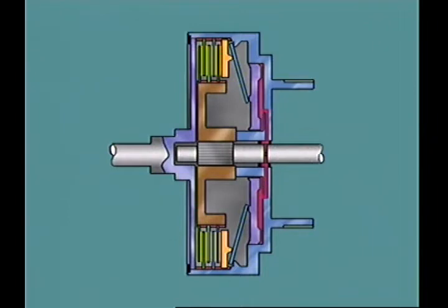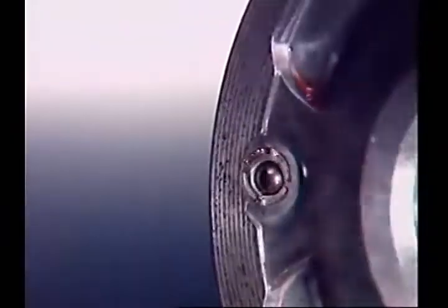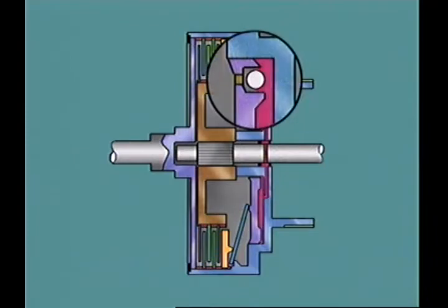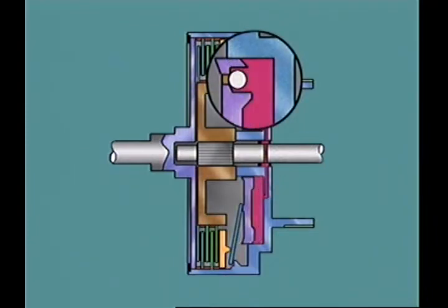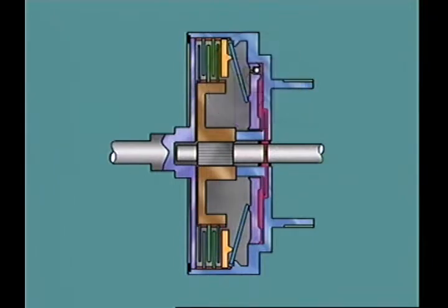This can occur if fluid is trapped in the clutch cylinder after release. Trapped fluid accumulates at the outer portion of the cylinder. At high speed and under the action of centrifugal force, this can produce enough pressure to effect partial application. This can be prevented by a pressure relief valve in the piston. It is normally a flat reed or ball check type, which is easily closed by the apply fluid. On release, the valve is unseated by the rotation of the assembly, letting fluid escape.